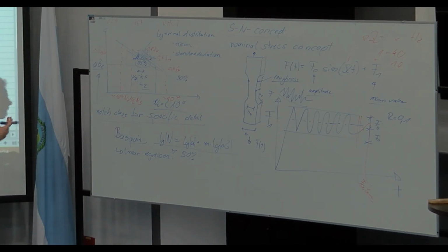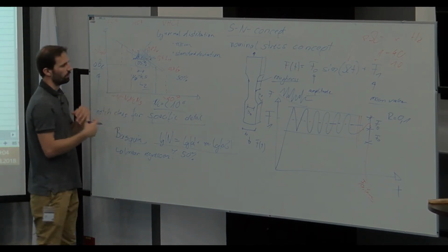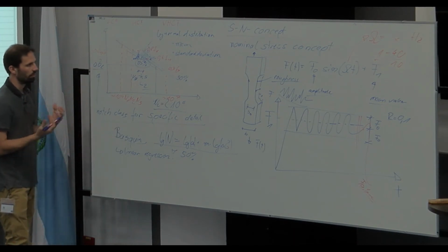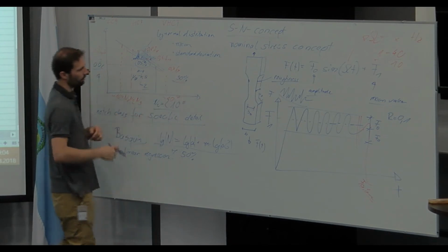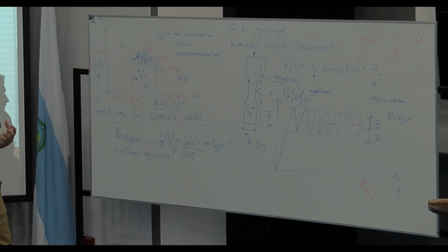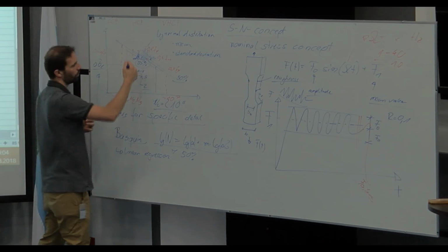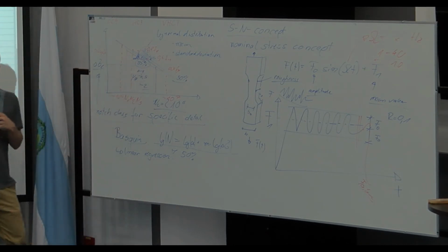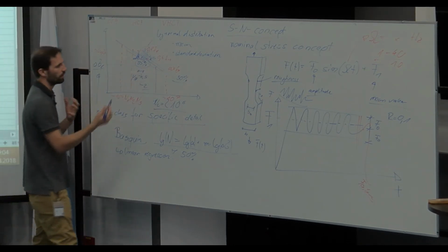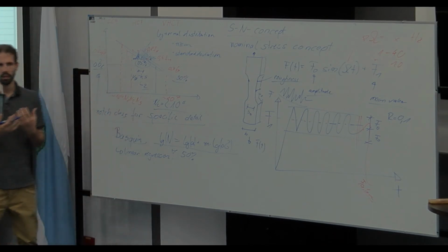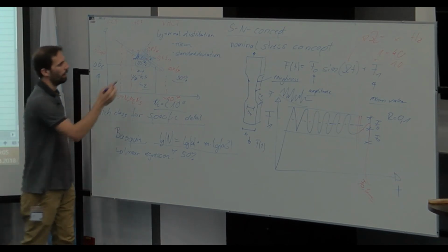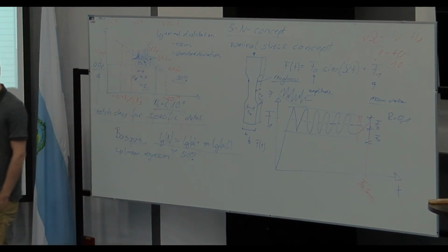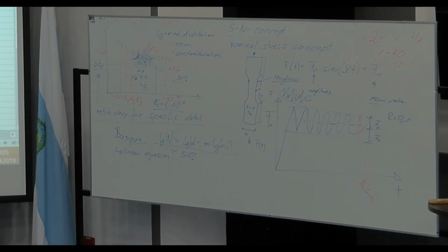And also at the same time, you have some reliability concept, some failure assessment where you say, okay, this is the mean value you have due to your testing, and then you shift your curve to the safe side, and you have to define here a quantile value to give you, at the same time, some information to have a good estimation due to the design in the first level.